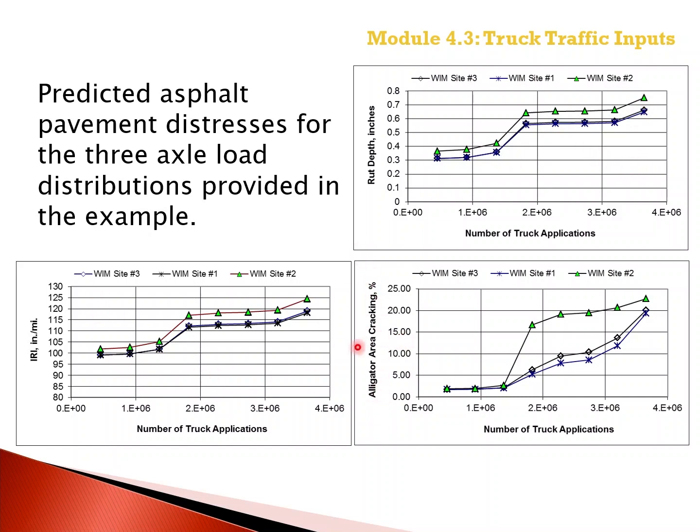Alligator cracking, bottom-up alligator cracking, shows WEM site 2, the closed triangle, predicts much more fatigue cracking, and WEM site 3, the open diamonds, predicts slightly more bottom-up fatigue cracking than WEM site number 1.